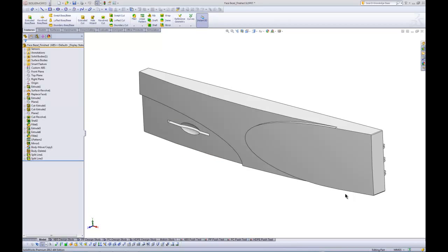So here we've got the actual faceplate. SolidWorks is nice in that it allows us to utilize different configurations, so we can have different configurations that represent the faceplate with different materials. And then once we've optimized the thickness, we can specify different thicknesses in each of those configurations to then go on and look at the ecological impact as well as the moldability, manufacturability basically. But again, as a starting point for us trying to extract information about this design, let's just look at a standard finite element analysis run.